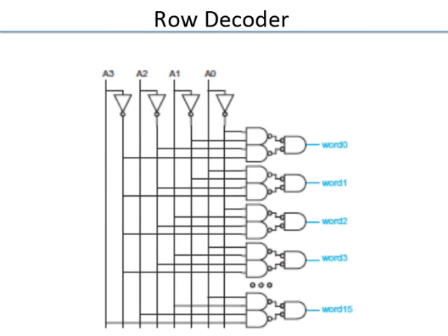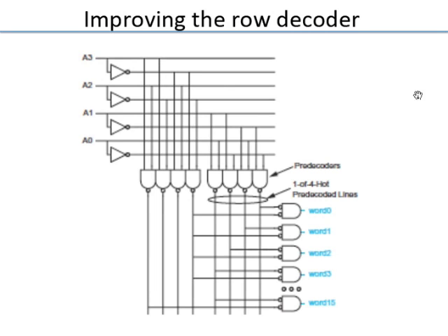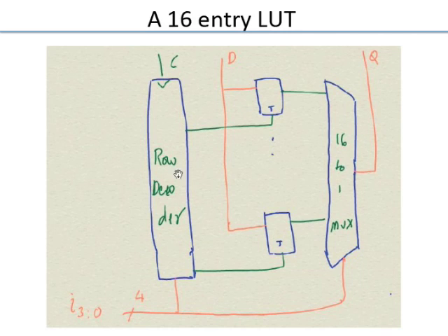For example, maybe I'll have a 3 input NAND gate here, and the write enable comes here. Maybe. Right? So there is a choice from a circuit perspective of how you implement it, but functionally you are just ANDing the address with the write enable signal, so that you write only when write enable is high.